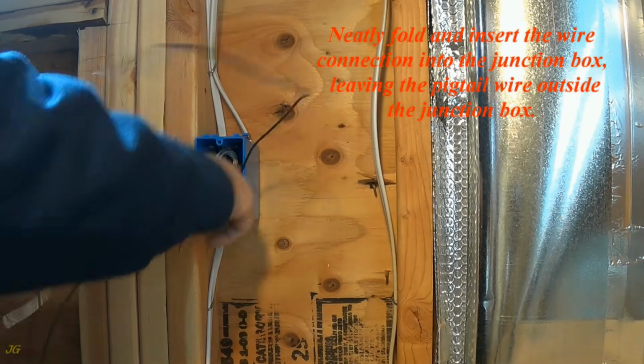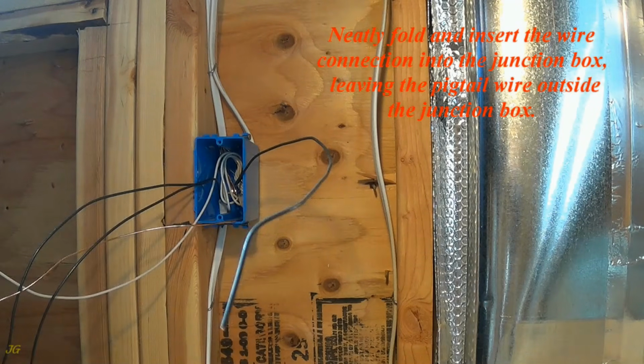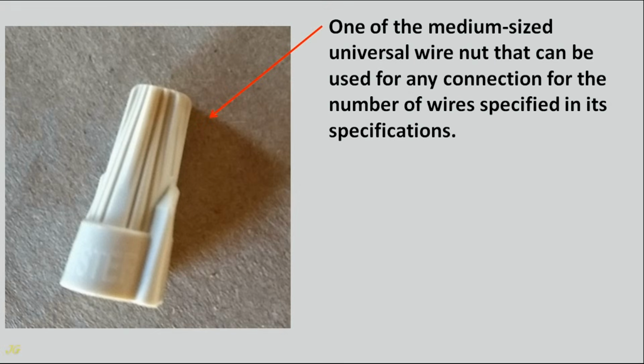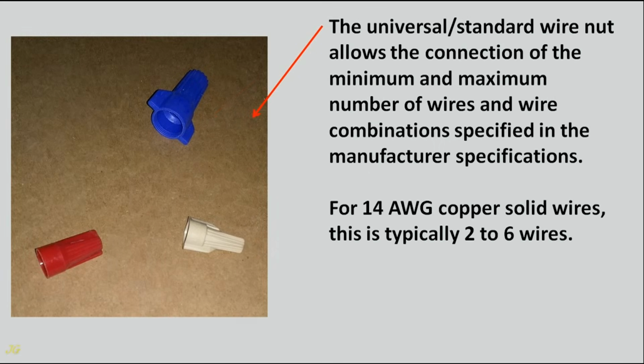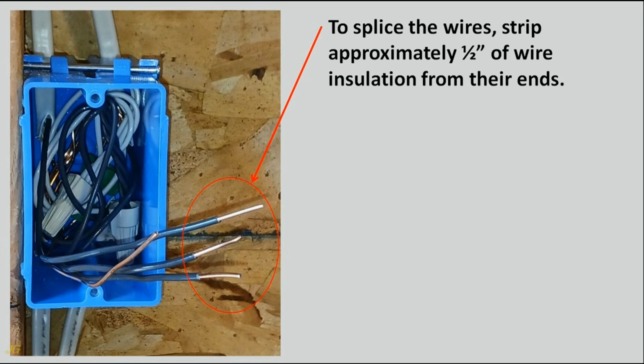Neatly fold and insert the wire connection into the junction box, leaving the pigtail wire outside the junction box. One of the medium-sized universal wire nuts can be used for any connection for the number of wires specified in its specifications. For 14-gauge copper solid wires, this is typically 2 to 6 wires. To splice the wires, strip approximately 1/2 inch of wire insulation from their ends.